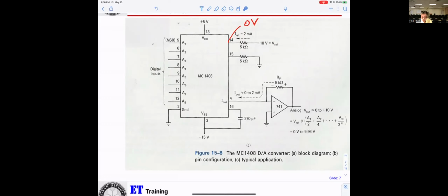If you want 10 volts, now they can be 5 volts. The only question is, if the 10-volt side was grounded, will that resistor bias any amount of voltage from pin 14? Meaning you're not going to have 0 volts. They must get 0. The thing is, inside here they do not try to adjust any voltage. They just short it to ground if they are working.